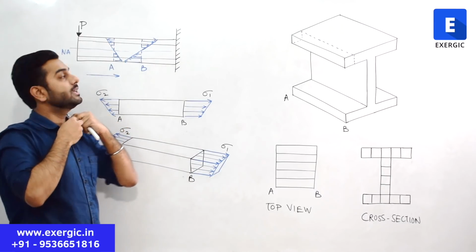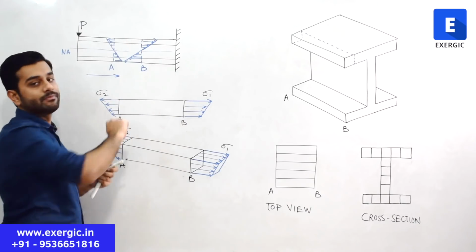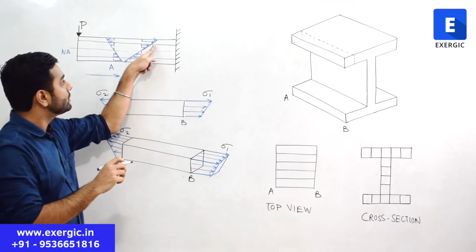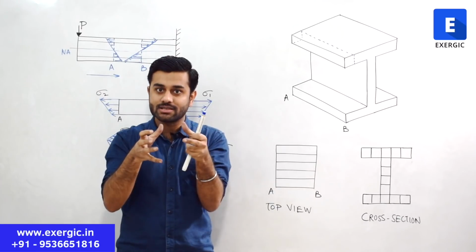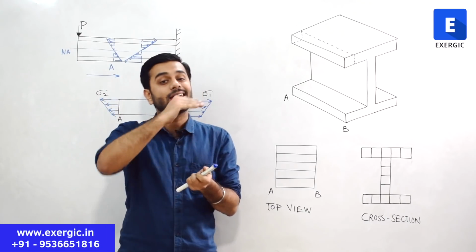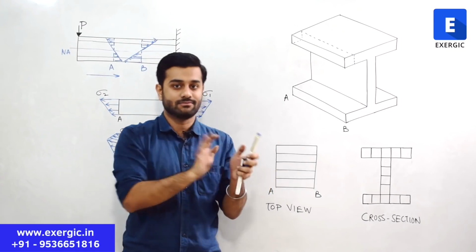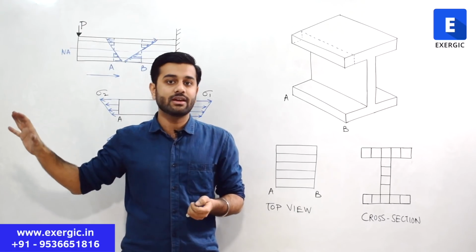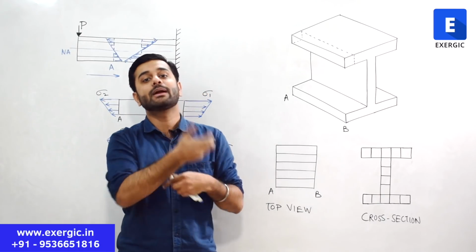And this is something that we already know, that at this section bending moment will be higher. Why does bending moment come? The bending moment is the resultant moment of all of these normal forces generated at the section B. Section B, section A, both will have tensile and compressive forces. The collection of those normal forces, both tensile and compression, are normal forces. The resultant of those normal forces is bending moment, right? I am sure you know these variations. We have already discussed these variations. The shear force is separate, but the normal forces, their resultant is bending moment, right?